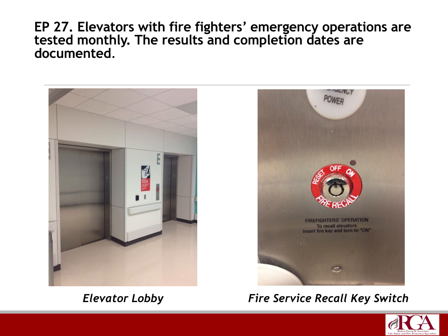Now, inside the elevator cab, there's a fireman's hat. You might have noticed a hat that will light up. Hopefully, you've never seen it lit up, because if that's the case, then that means that car is no longer safe to use. That's the purpose of the fireman's hat. It's for firefighters. If it lights up, it lets firefighters know that the elevator car specifically, or shaft, is no longer safe to be in, because either A, the elevator machine room has been compromised, there's been smoke detected in there, or a fire, and/or in the actual shaft.